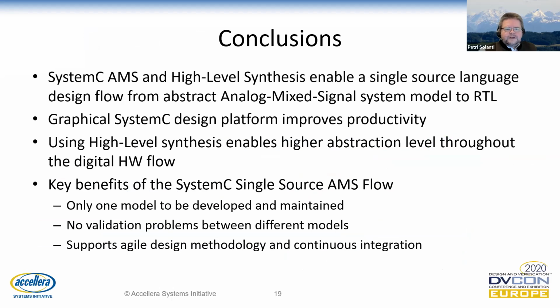SystemC is the language that enables a single source language design from abstract behavioral description of an analog mixed signal system to RTL. A graphical SystemC design platform reduces the burden of writing the module architecture and connections, allowing the designer to focus on the behavior. High-level synthesis removes the need for RTL language and allows maintaining a high abstraction level throughout the whole digital hardware flow.